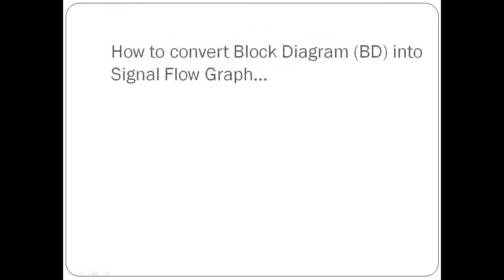If you are done with this, now let us try to understand a different aspect of solving numericals on block diagram reduction technique. For example, it may be possible that in some cases the block diagram is so complicated that it is very difficult to solve and analyze the system by using BDRT rules. Then what we need to do, we will convert the given block diagram into its equivalent signal flow graph and then apply the concept of Mason's gain formula to solve that particular numerical.